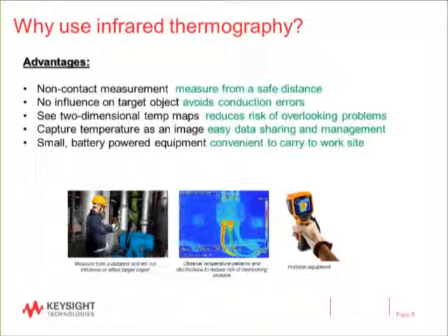Well, in general, the advantages of infrared thermography are non-contact measurement, where we can measure from a distance while the system is running. Secondly, since the thermal imager only measures IR energy emitted from an object, it will not affect the target object in any way. Thirdly, we can observe the temperature patterns and distributions, and this is an advantage over the use of thermocouples, which determine temperature only at specific spots. This also reduces the risk of overlooking problems that might occur in other areas within the equipment or machine. We can also capture the data and IR images for reporting and filing purposes.